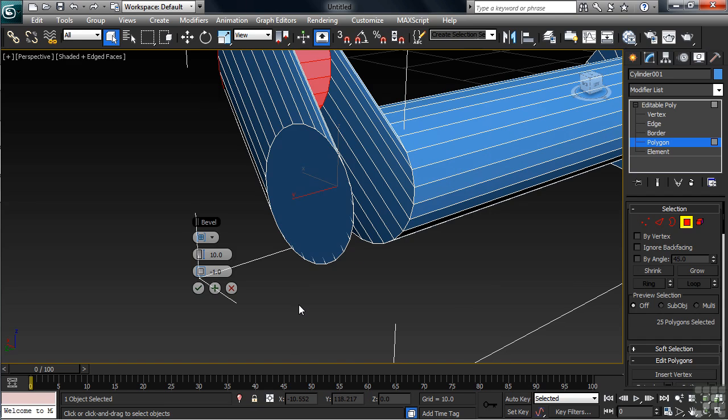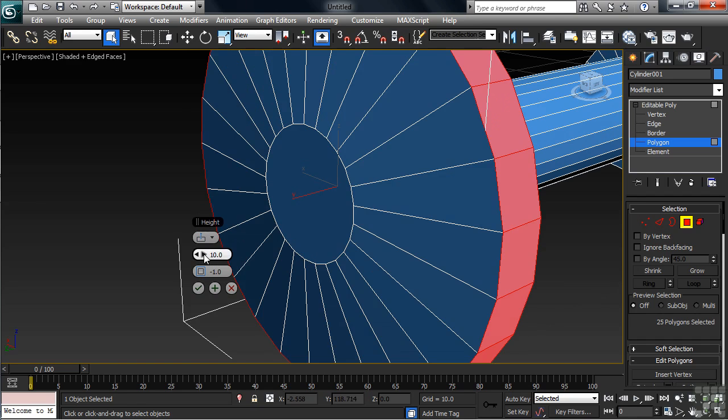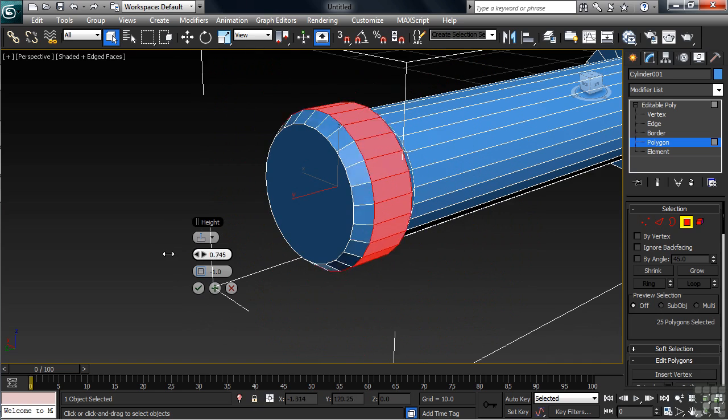In the caddy on the second level, change by local normal. The third level will take down quite a ways. Then, why don't we force in the value by double-clicking and typing 0.3. For the outline, let's take that to -0.5. Okay, we're going to want to agree to what we've done, but we want to continue to add another bevel. This time around, on the bottom row, instead of clicking on the green check mark, we'll go to the middle, clicking on the green plus sign.